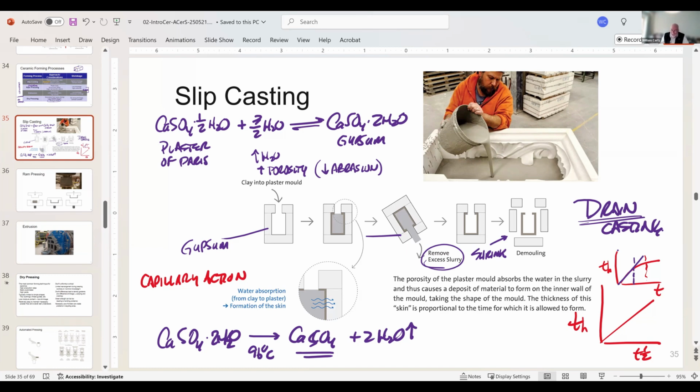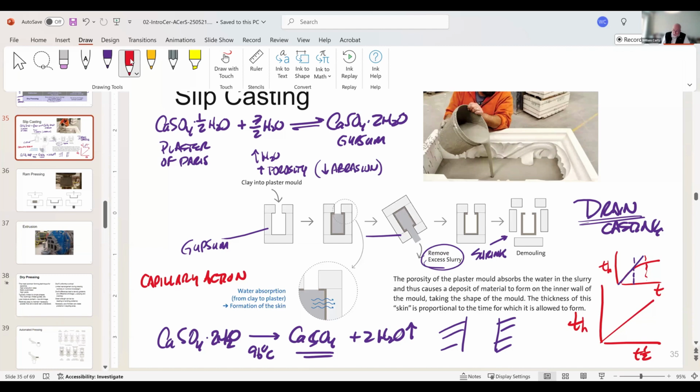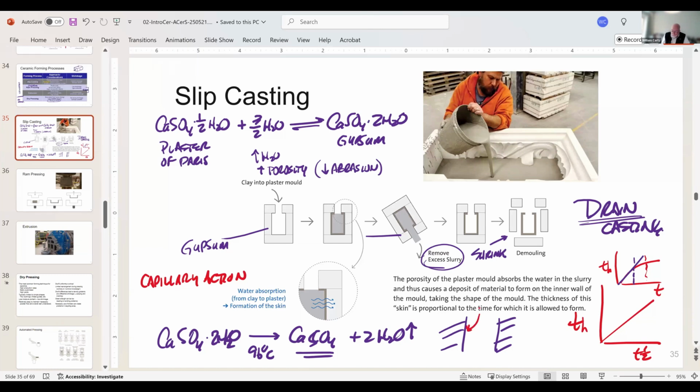In sanitary ware, they don't drain the system. They cast two walls. So you have your mold and your mold, and you bring in your slurry. The slurry comes in and casts into both sides at the same time. When you get done, you have a parting line down the middle that's usually not too bad, and you can see it in cast layers.